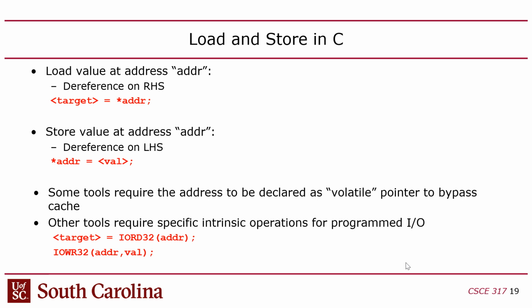Okay, now how about loads and stores? I mentioned loading and storing. I said load and store instruction. That's how you write and read control registers. And you might be thinking, yeah, if it's assembly language, but there's no load and store in C. Correct, there is not. The way C handles loads and stores is through a star operator, the indirection operator. Dereference operator, I should say, dereferencing, which looks nothing like a load or store.